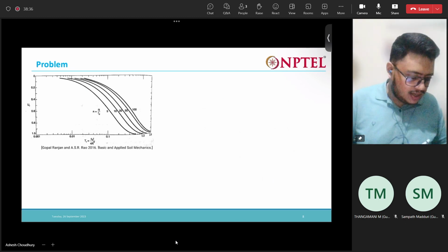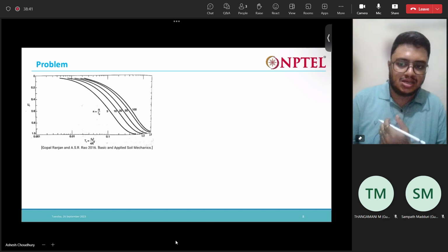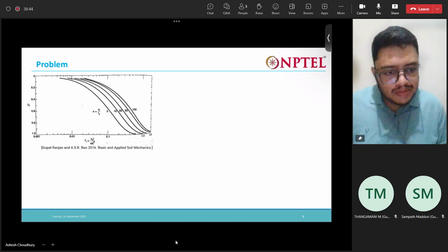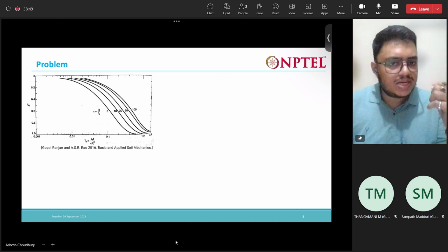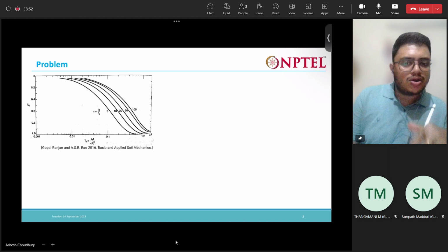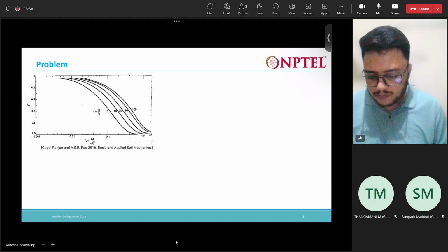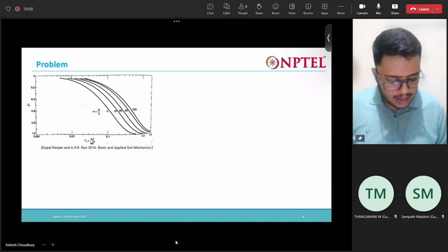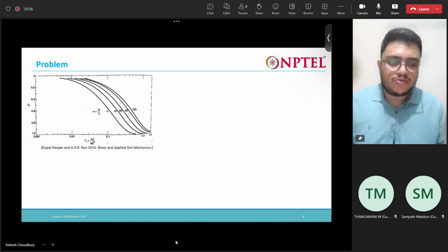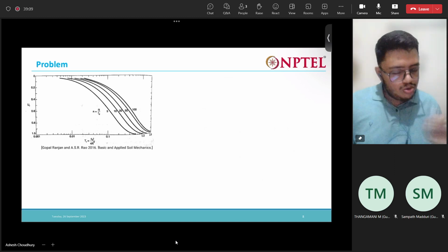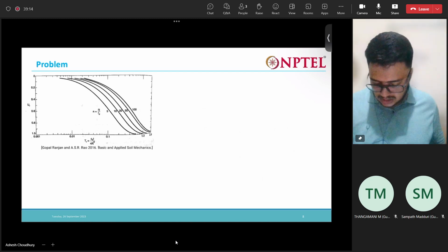Now when you are using the sand drains also, 89% consolidation is occurring within the same time, 6 months. Before, only 27.5 mm settlement would occur in 6 months with only vertical drainage. Now due to the introduction of sand drains, 162 times 0.89, that is 144 mm settlement will occur. So almost 90% settlement will occur within the same 6 months.